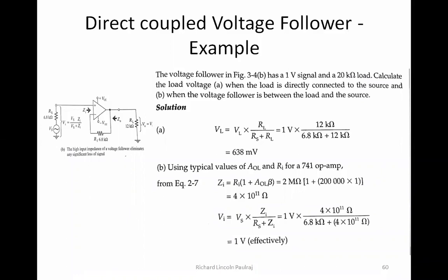Very intelligently you should be able to pick up resistance values, the impedance, and if they ask for gains, you can take the gain values, or slew rate, for example, if it's not given, then you can take about 0.5. Ultimately, if you know the formula properly, you will be able to find out exactly what you need to extract.